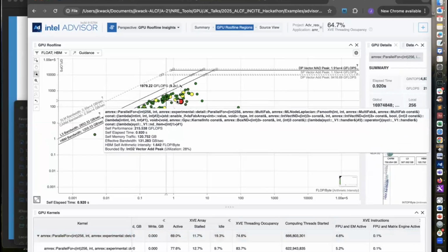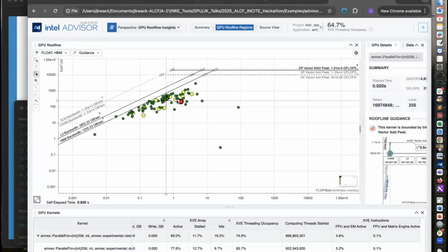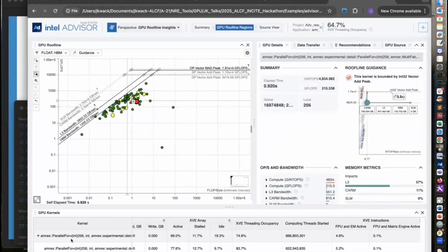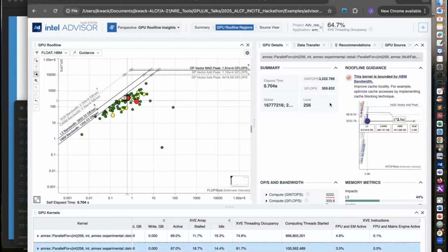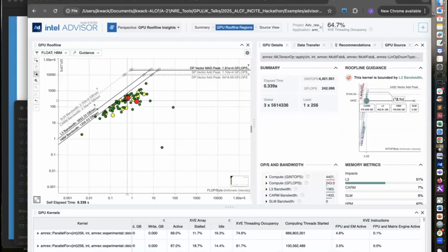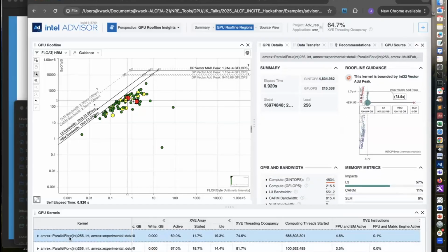Again, this is the difference between the approaches of VTune and Advisor. VTune provides a lot of additional knobs. Advisor collects pre-configured data and provides some performance tips based on that measurement, right? So this is a quick overview of Advisor. If you choose a different kernel here, the GPU details keep changing, right? So you can play around with your hot kernel using the analysis.